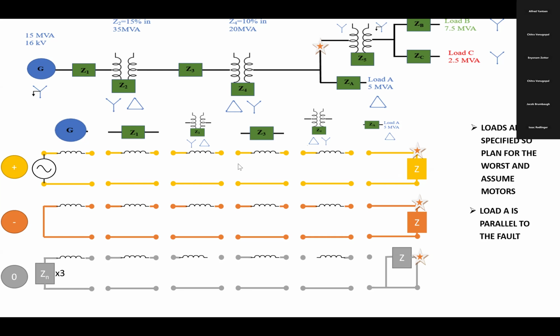So this side, positive sequence, negative sequence, just the impedance. Whereas for zero sequence, this side is delta, so it should be connected by the impedance. Sorry, here. This side must be connected by the impedance, but it's a delta, no common ground, so that should be left open. Whereas the other side is star, so the other side must be connected with the impedance. Right. Then this side, there is no line impedance given here. It's going directly to the, let's look at this part. Okay. So the fault is happening here. The star is the place where the fault is happening.